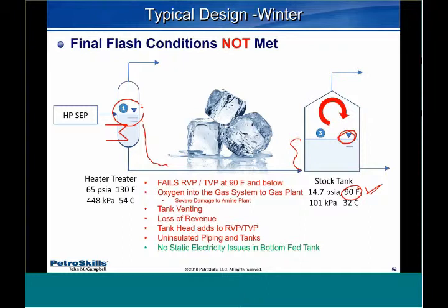So this particular design also has an issue with internal reflux. If you do heat the tanks and it's minus 20 out or 0 or 40, propane and butane are going to condense on the shell and never make it into the vapor recovery system, and it's going to fall down, and it's a dynamic problem. It's going to continue to build in the system.